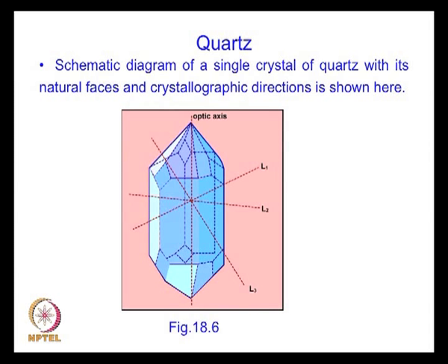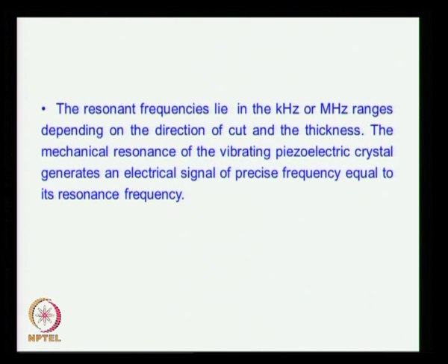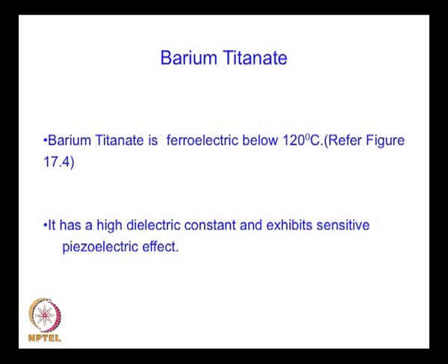This figure shows a single crystal of quartz in which the different cuts which are employed for production of piezoelectric slices with different frequencies are shown. Now, the reference frequencies can lie in the kilohertz or megahertz ranges, depending on the direction of cut and the thickness of the crystal. So, that is how the quartz is used in an oscillator.